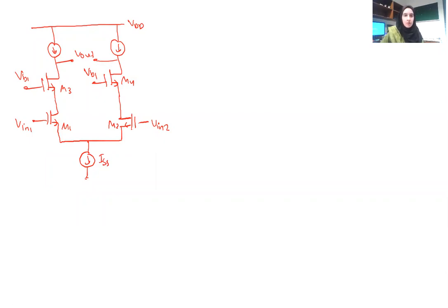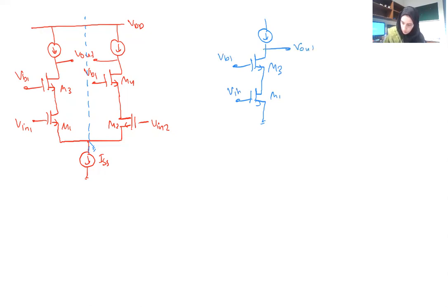this differential amplifier. So since both sides of it are symmetric, we can draw the symmetry line. And we said any point that lies on this symmetry line will be turned to a virtual ground, and then we can draw half of the circuit. So we will just have this, M3, this. You can take either half and find just the gain for that half because both are symmetric.